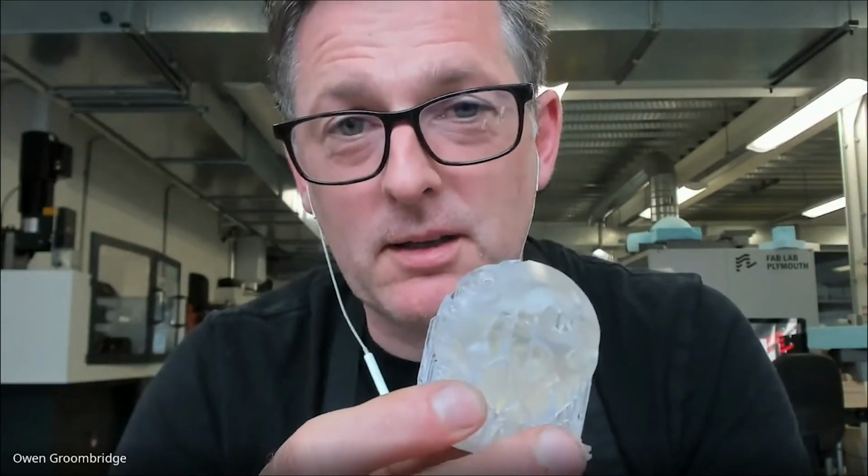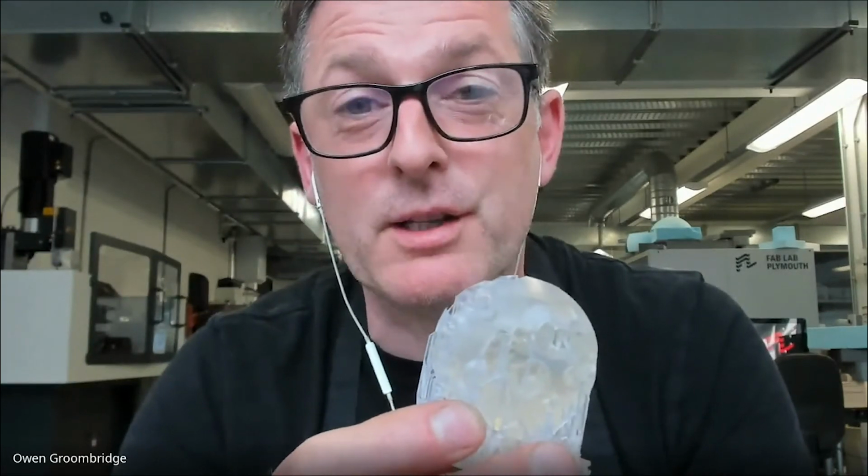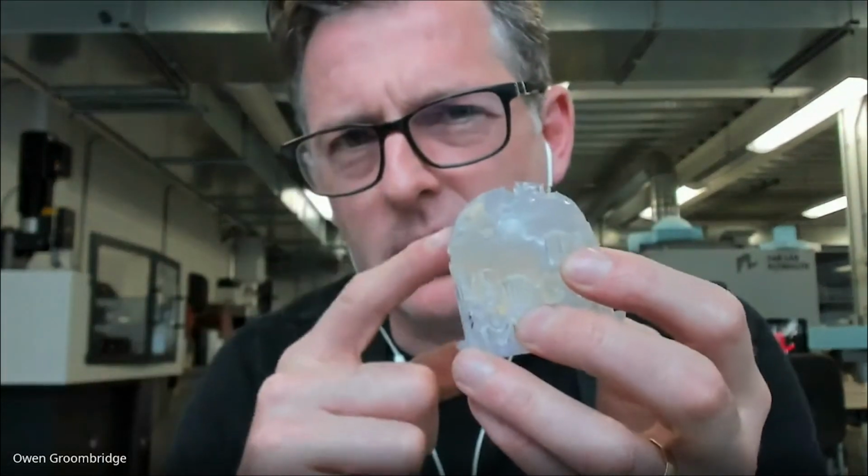And this stuff is a resin. It's goopy and sticky. You have to use isopropyl alcohol, and believe me, 14 months ago isopropyl alcohol globally was very expensive, and we use a lot of it to clean this stuff up. The alcohol is bad for you because it absorbs through your skin into your bloodstream, but also the resin just gets on your hands and it's messy stuff. So that's the main con with these kinds of materials. But in terms of definition, you get superb definition with things like this SLA printing.